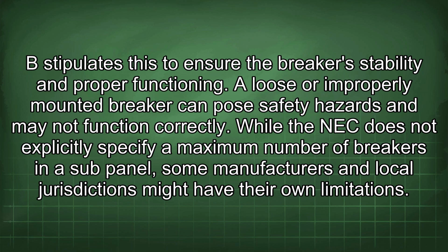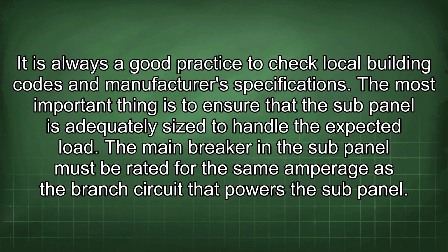While the NEC does not explicitly specify a maximum number of breakers in a sub-panel, some manufacturers and local jurisdictions might have their own limitations. It is always a good practice to check local building codes and manufacturers' specifications. The most important thing is to ensure that the sub-panel is adequately sized to handle the expected load.